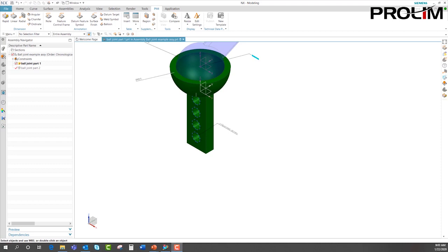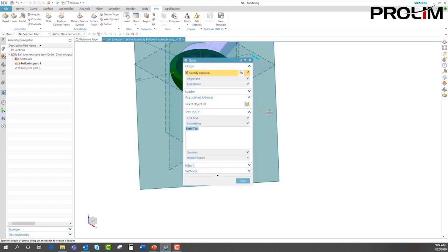We're going to continue on with some more PMI and drafting enhancements. This one here is a note enhancement. This allows us to insert NX symbols or Unicodes using a new method called insert symbol. And we'll go ahead and do one of these real quick. So if we come over here and hit note and go under format, we now have this symbol here, insert symbol.